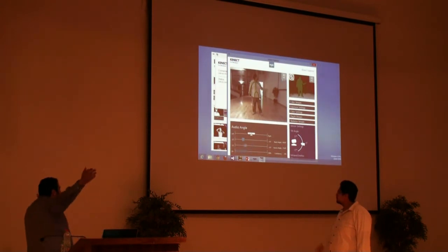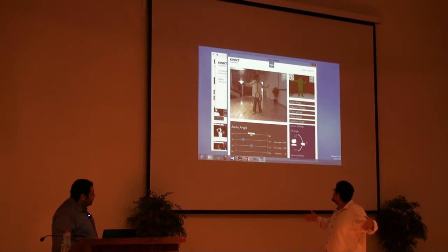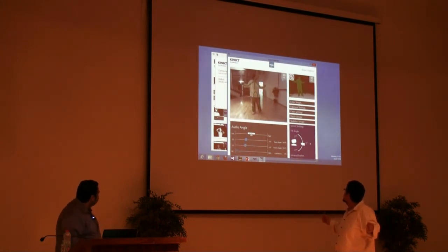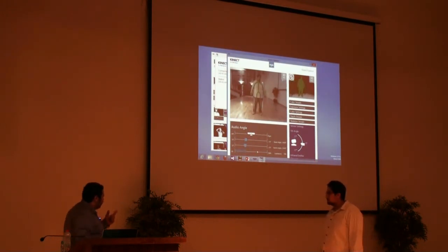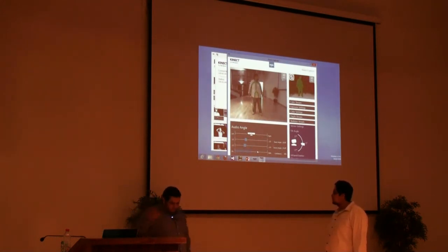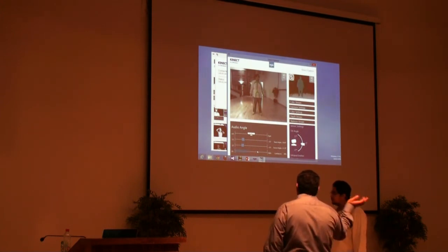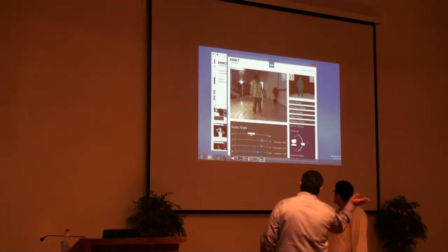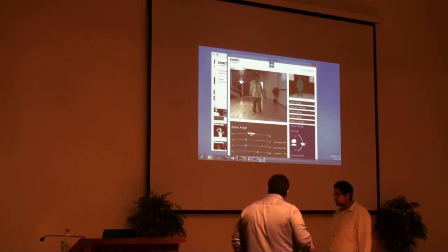Try to move around, check, it's working, right? Here I control the motor for tilting. As I speak, you can see that it is recognizing the direction. If I talk from the other side, it should go to the right. It's detecting where the sound is coming from.